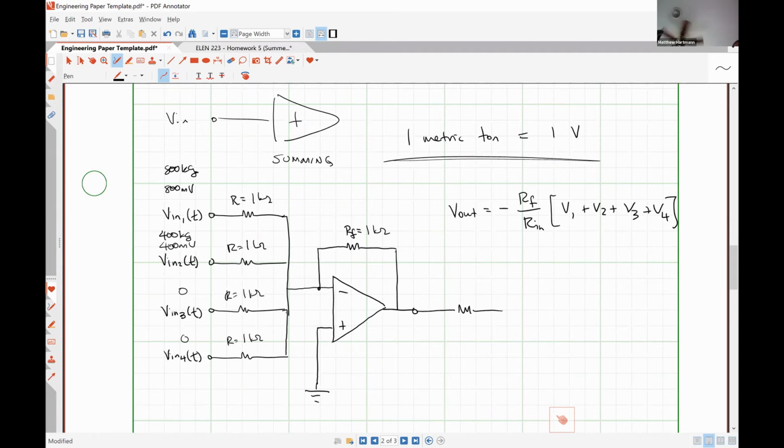So we'll feed the output of our summing amplifier into an inverting op amp. So there is our resistor, and here's our output voltage for the system. So what resistor value should I use for the inverting op amp, where I have another feedback resistor, let's call it R2?